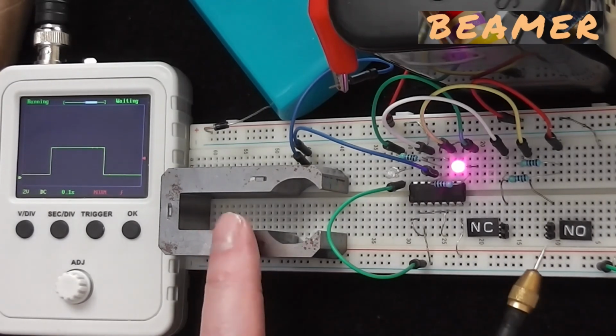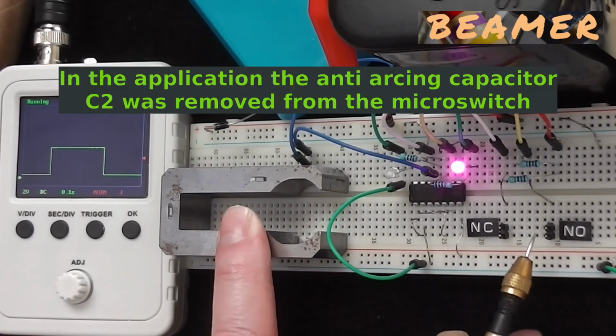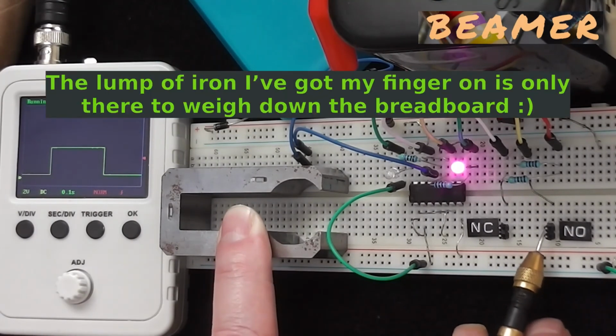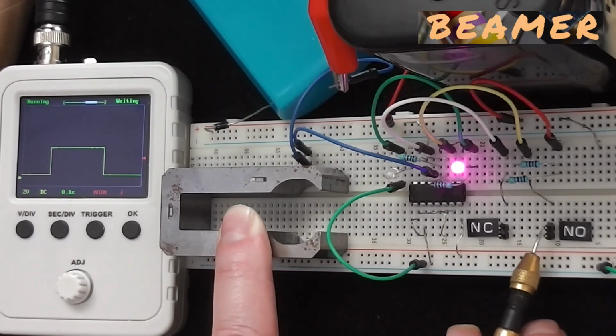So the micro switch, when the mechanical shaft actuator was not touching the micro switch, the wiper would be on the normally open contact, and it doesn't matter how many times I'm pulsing onto this contact with the wiper, the state remains the same.